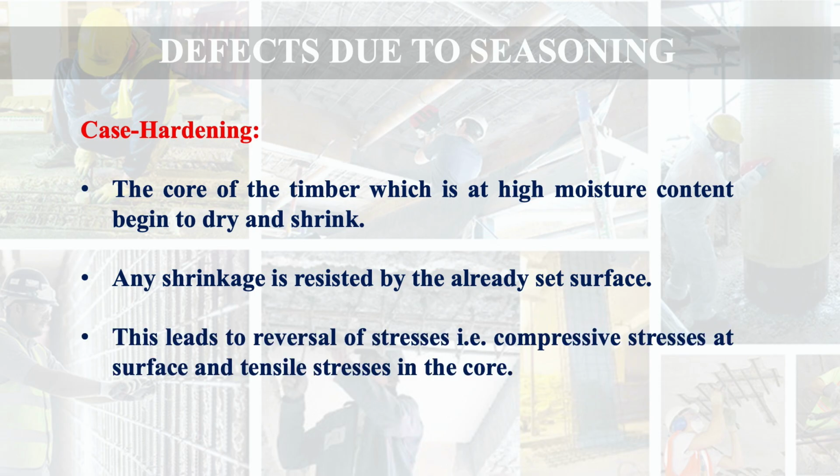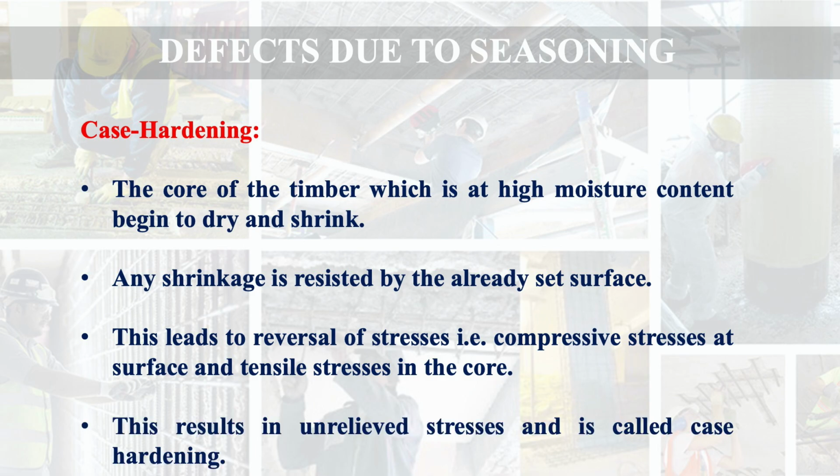This leads to reversed stresses, compression stresses on the surface, and tension stresses in the core. This results in unrelieved stresses called case hardening.